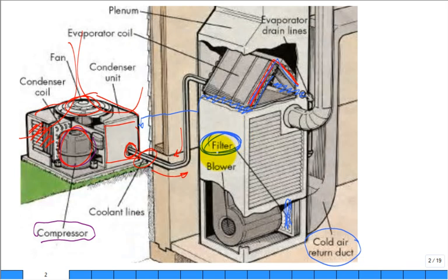Otherwise, get your money in the bank ready to pay for when your air conditioner system goes down because you didn't keep the filter clean by replacing it often, because that's what will happen. What will happen is all that lint, dog hair, cat hair, your hair, junk, dust, instead of collecting on the filter and then being thrown away every month or 2 months whenever you change your filter, it'll collect right up here where you can't really get to it easily, and the serviceman can't get to it easy. And they'll have to cut that A coil out, and they'll have to take it out and clean it and then put it back in, and that'll cost you, probably now about $1,000.